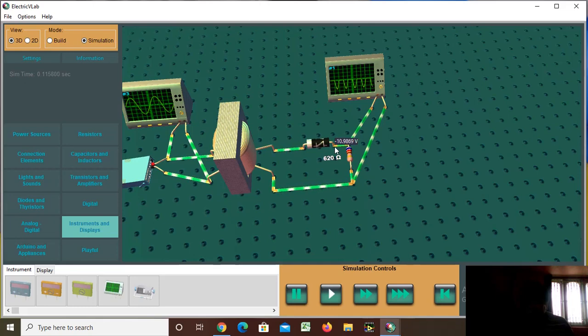Now I'll just keep it here. Now we are getting some voltage. Now it is reducing. See, it reaches 0. When it reaches 0, for the positive half cycle it becomes 0, and for the negative half cycle you can observe the sign. That sign indicates it is passing the negative half cycle. Please observe the sign and the direction. This is the direction, the current is flowing in the reverse direction. You should understand that it is passing the negative half cycle.